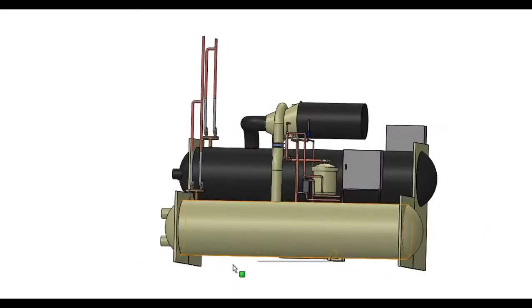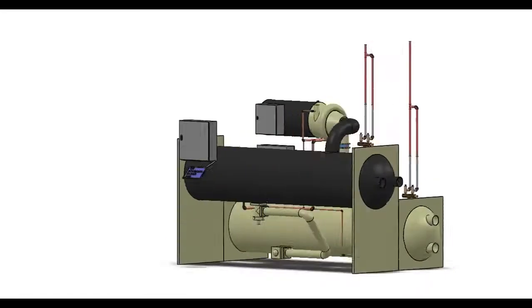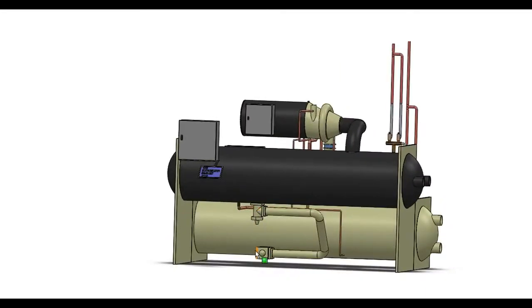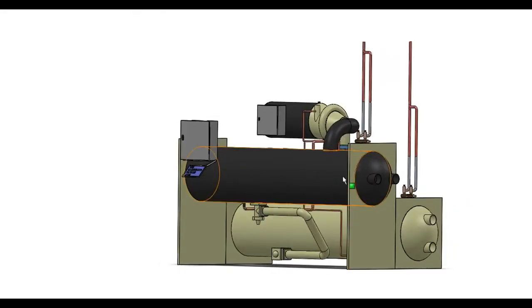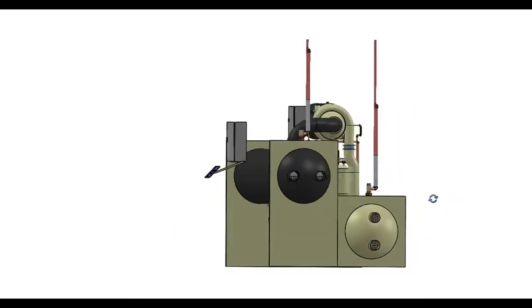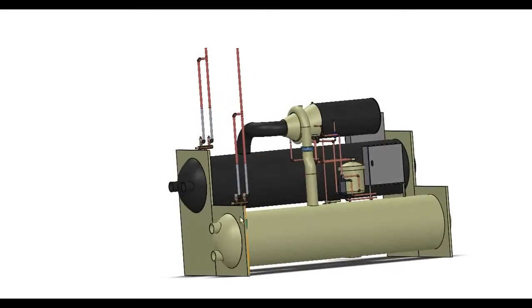So that's the condenser, the expansion valve where the refrigerant passes through this and into the evaporator, and that then leaves there and passes back into the compressor. Remember, the condenser water enters and leaves in the condenser, and the chilled water enters and leaves through the evaporator there.